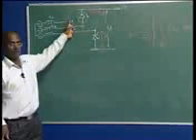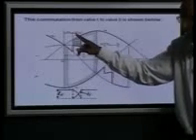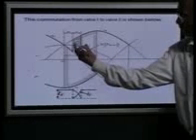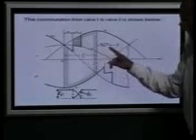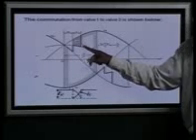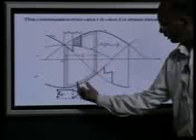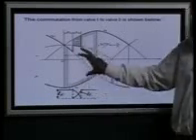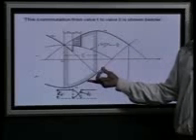Now 3 gets the pulse at this point after alpha degree delay. In this period u, you can see the upper limb valve has minus EC by 2 coming here, and in the lower one EC is continuing. So in this period u it is this voltage, and for the remaining period EB minus EC is appearing, and this is repeated again.